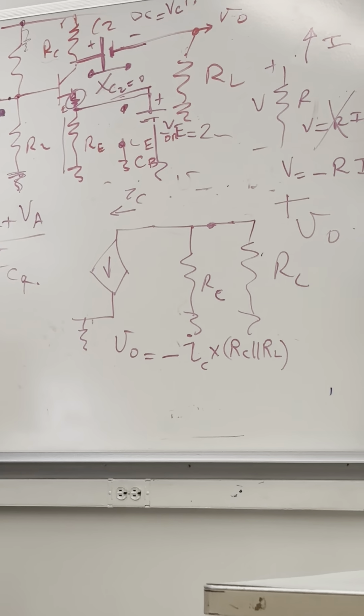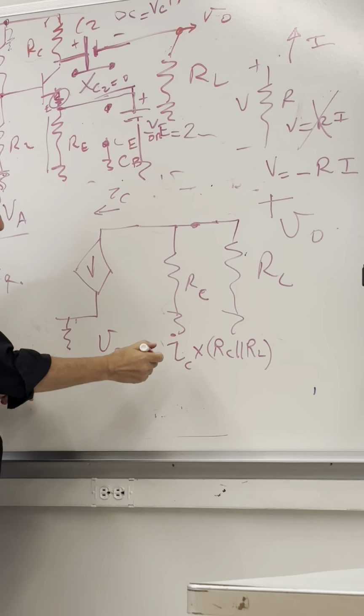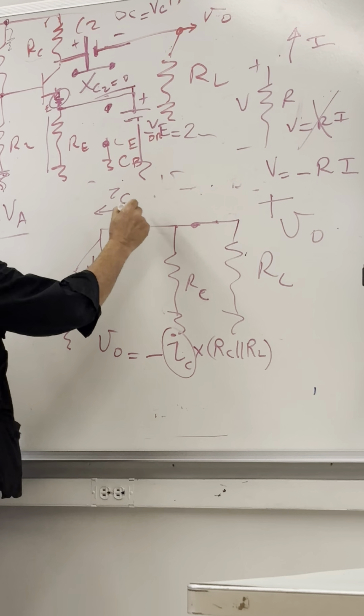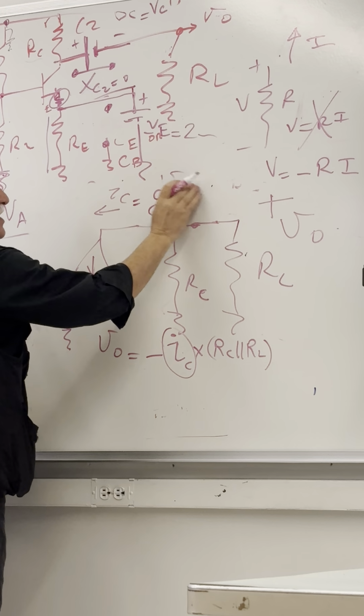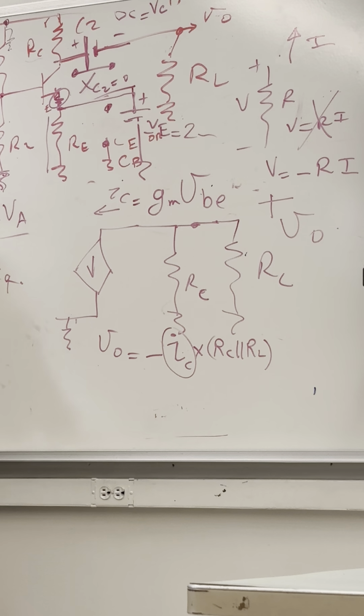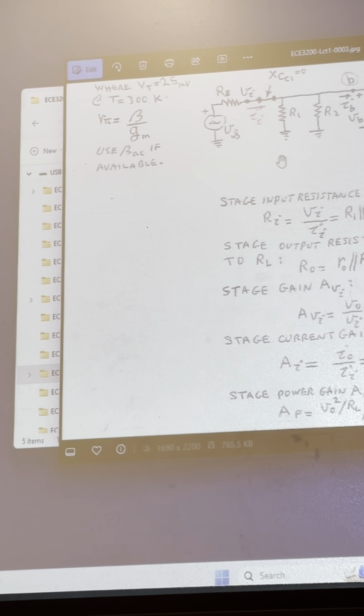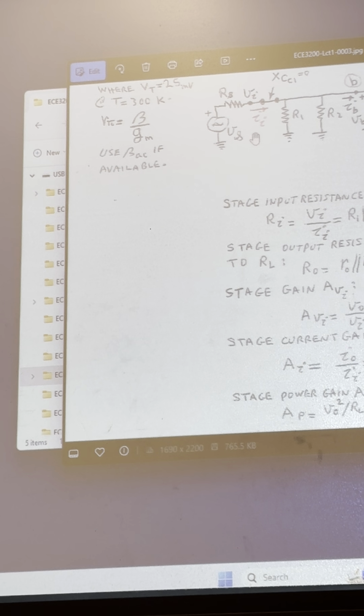You know, the laws of energy will be violated there. So when it comes to that, you get that minus. But look, what is minus IC? IC is gm multiplied by VBE, the base emitter voltage. But check here: the change in the base emitter voltage is exactly the same as the change of voltage at that node with respect to ground, because this voltage is referenced to the ground. That node is the same as this node. So VBE is identical to VI.